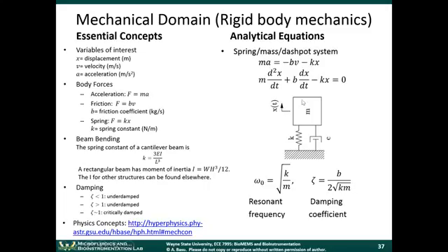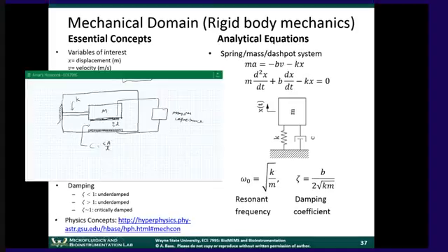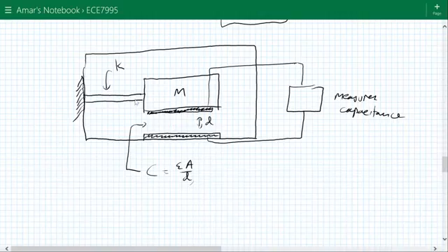The first force we're going to talk about is that the force exerted on this mass is equal to mass times acceleration, whatever acceleration was being applied to the entire system. That's the first force on this mass. The second force is that the mass is attached to a spring. In this case, the mass was connected to some sort of beam element. These beam elements can be microfabricated. This beam element is going to resist the mass from moving. It acts like a spring.